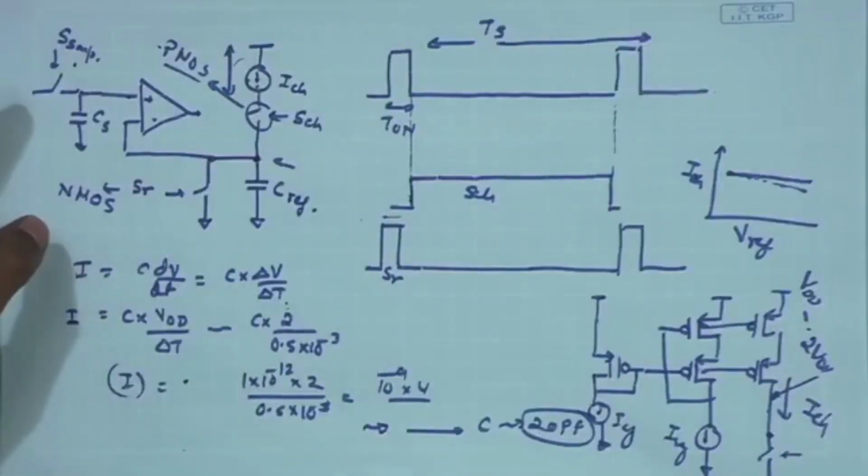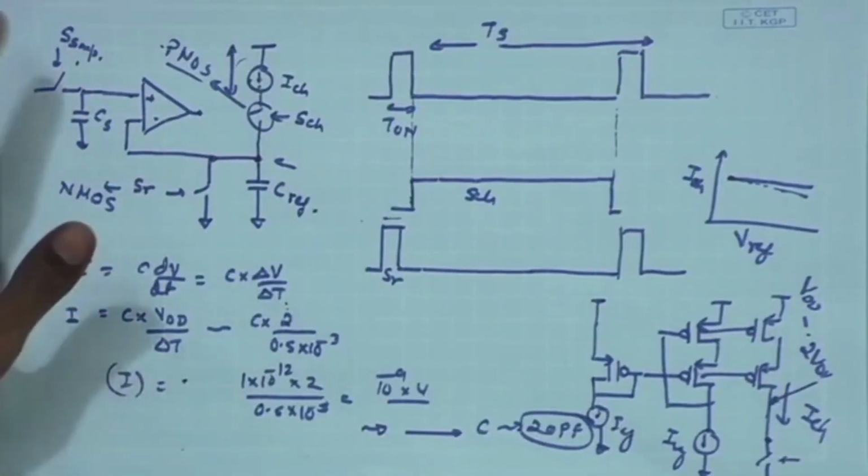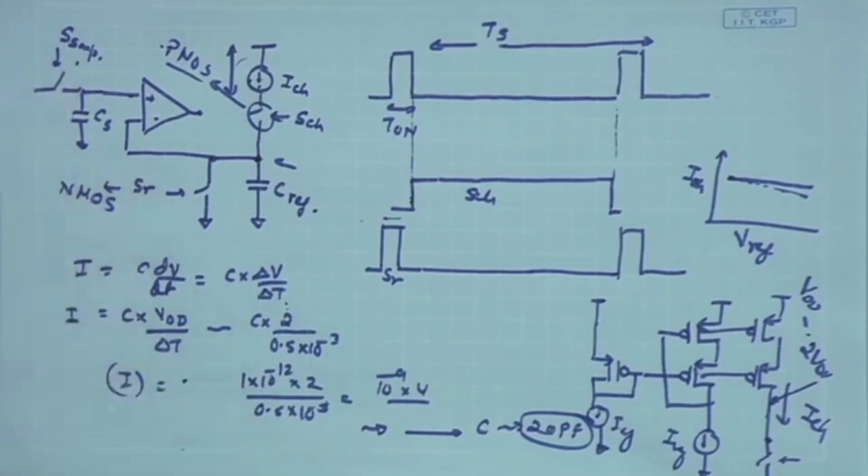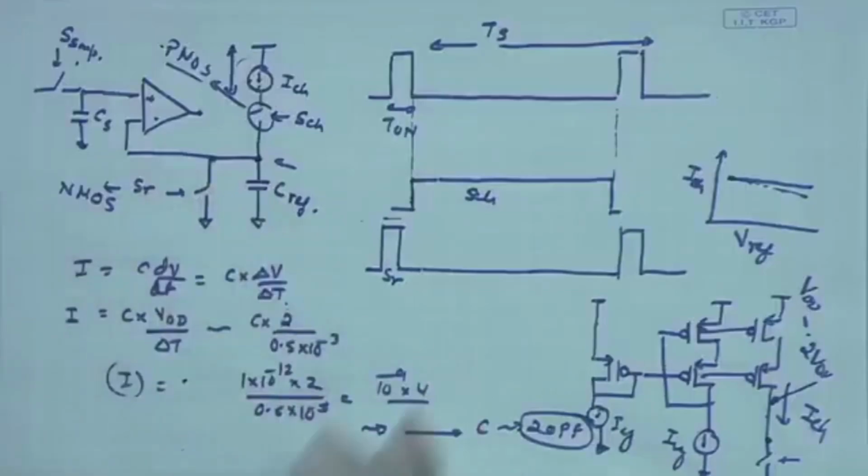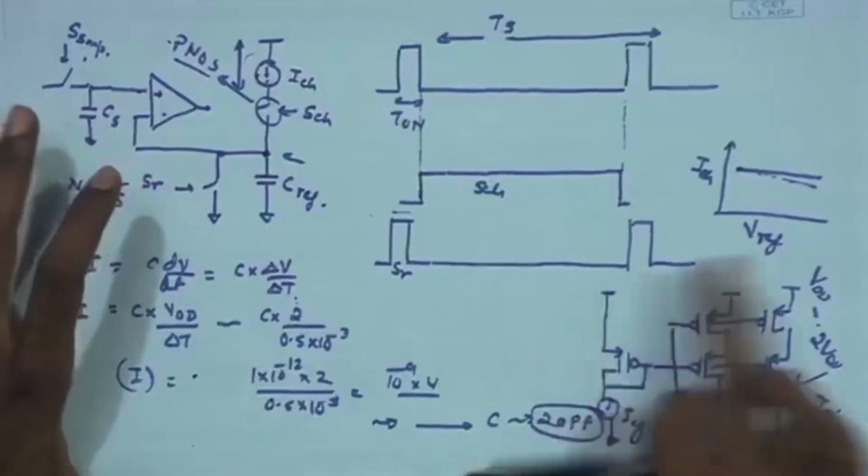We need to make full swing at the input, the entire rail-to-rail swing, and for that another constraint comes into the picture. If we make some architectural modification, adding other modules to make the input range large, we will see that other comparator non-idealities like offset and mismatch can create further difficulties, and we may need to address those issues by having appropriate mechanisms to cancel out the non-idealities.